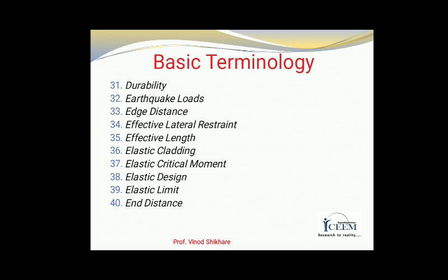Then elastic limit. It is the stress below which the material regains its original size and shape when the load is removed. In steel design, it is taken as the yield stress.